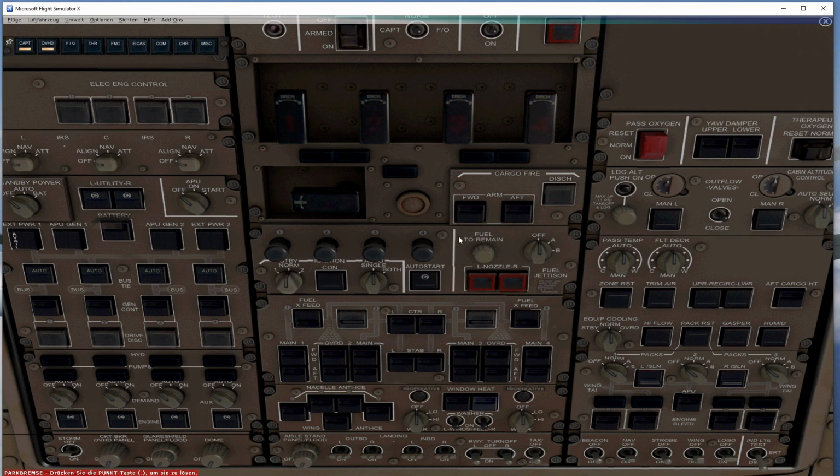Well, this is the fuel jettison system. The landing weight of our airplanes is a lot lower than the takeoff weight, so you can land at max takeoff weight, but it's definitely an overweight landing and should be avoided. So if it's not an emergency where you have to land immediately, you will fly somewhere, dump some fuel, and then land again close to or below, or even slightly above, max landing weight.